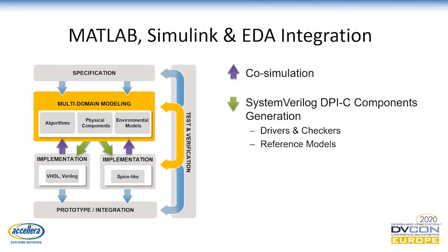As we can generate C code from practically any MATLAB function or any Simulink block, the DPI-C flow allows us to simulate together in one simulation, be it digital or analog, all components together as a whole design. Already in early stages, when not all analog and digital block implementations are available. So already in the prototyping stage or the algorithm building before it's really elaborated, etc.